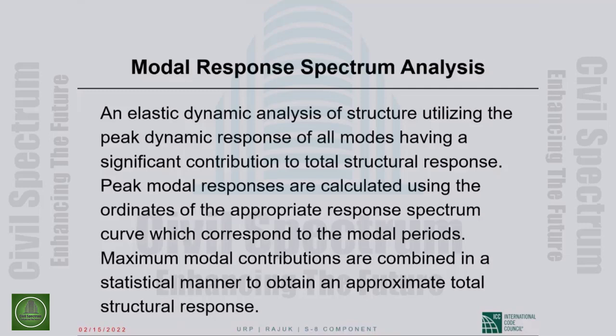So modal response spectrum analysis is an elastic dynamic analysis of structure utilizing the peak dynamic response of all modes having a significant contribution to the total structural response. So a 100-story building has 100 modes, but all 100 modes do not contribute significantly to structural response. It will be only the first few modes, I don't know, maybe the first 10. Those are the ones we consider. Okay, and then how many to consider is specified. We will come to that.